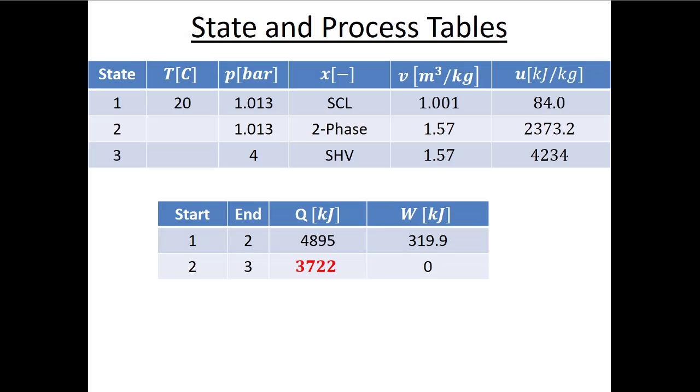So this is work out, which means that the system is doing work on the surroundings, which is true in this case because the water vapor inside of our piston is expanding. And as it expands in this first process, it's pushing that piston out. So that's the work being done by this boiling water expanding the system. So we are expecting work out here. And if work in is negative, then work out must be positive. So the sign there makes sense too.